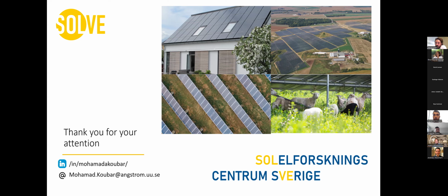But we want to investigate more the other ancillary services in a real-time model. So operating on secondary reserve or mFRR, and here the discharge will be higher. So of course it could have some potential, but here the focus is on the primary reserve and on the optimized case, which is the FCRD.